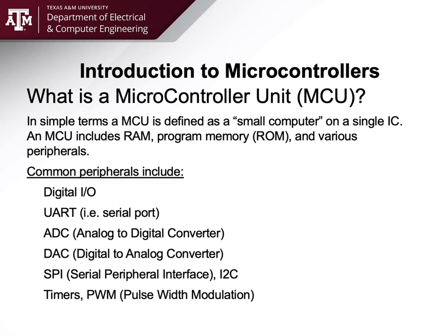basically like flash today would be the case, your read-only memory, and then various peripherals such as general purpose I/O, GPIO pins, digital I/O, and UARTs. If you're new to this class and just getting into your project, you might not know what a UART is. A UART is basically known as a serial port. It stands for Universal Asynchronous Receiver Transmitter, and this is a simple communications mechanism to transmit data serially, one bit at a time.